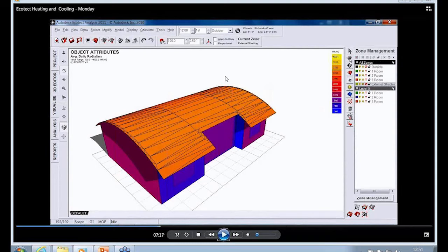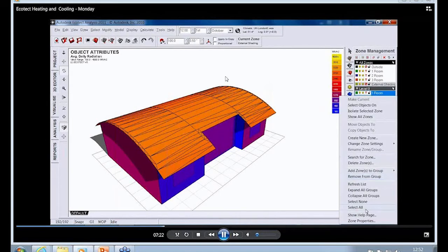We went through the process of defining rooms within Revit. Those have been imported in. Now we're going to define the properties of those rooms. In the context of Ecotect, those rooms have been converted over into zones. So there were 3 rooms within Revit, and they've been converted over into 3 zones within Ecotect. And here you can see those 3. So in this case, what I'm going to do is to combine 2, and then we can take a look at the properties of those zones.